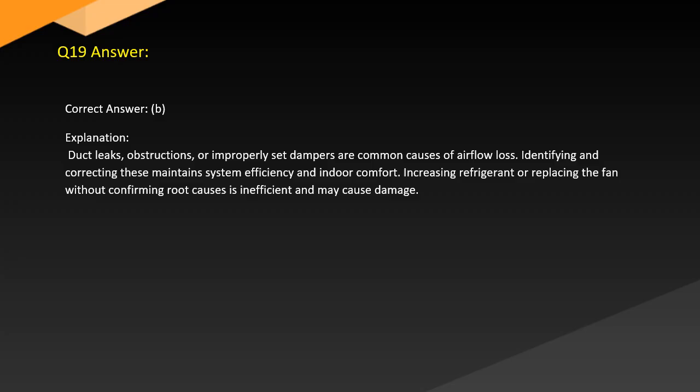Answer. Correct answer: B. Explanation. Duct leaks, obstructions, or improperly set dampers are common causes of airflow loss. Identifying and correcting these maintains system efficiency and indoor comfort. Increasing refrigerant or replacing the fan without confirming root causes is inefficient and may cause damage.